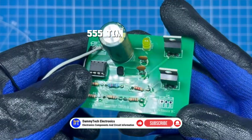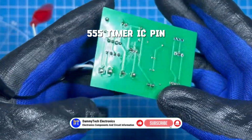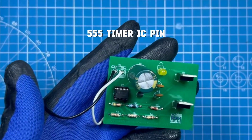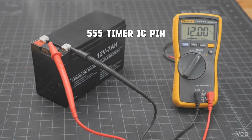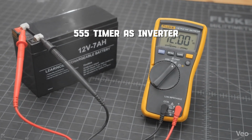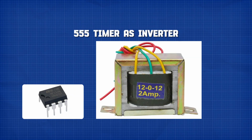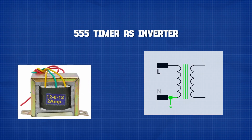Now let's use a 555 timer to design an interesting project, a 12 volt to 220 volt inverter circuit. So basically a 12 volt battery gives DC voltage, but the major electrical component that I use to step up voltage is a transformer. But a transformer cannot step up pure DC properly. A transformer needs a changing signal, which is called alternating current. So we need to switch the 12 volt DC very fast so the transformer can work. This is where the 555 timer comes in.